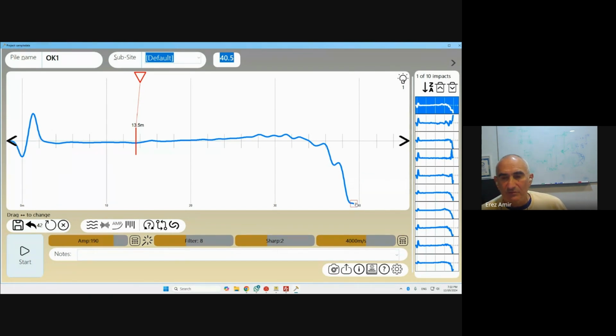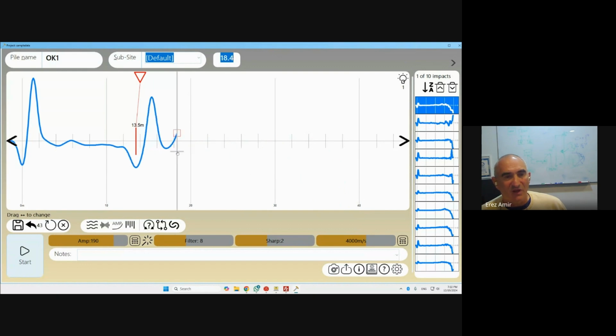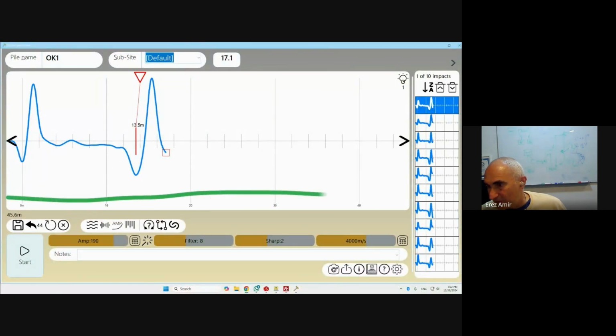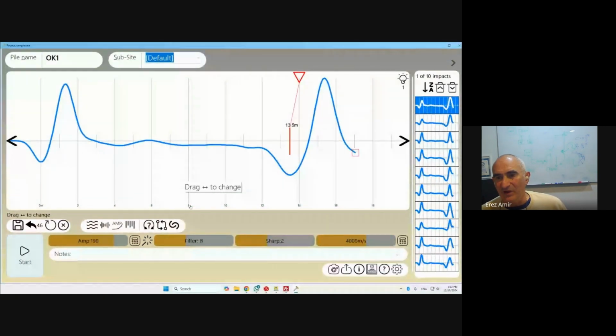So it's important to set the planned length to approximately the right length. Otherwise, you're not going to get enough information. Now, after we got the planned length correctly, we're going to put this 2 or 3 meters after the planned length, because probably that's where the end is going to be, within this range. Okay, we played with the scale. What we can do here is double click the scale numbers. I just double click that and it sets the scale for me automatically to about 3 meters beyond the end of line.